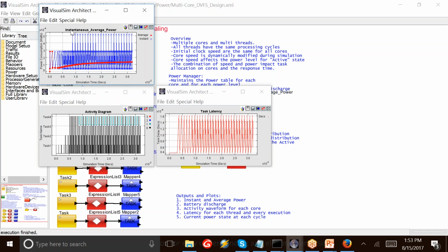We went from about 1 milliwatt of power to about half a milliwatt of power. Notice the average didn't really change all that much. It's still very close to the same number. But then the peak power dropped off because we're able to offset these substantially. So as a result of doing that, we're actually able to improve the power performance of our system.